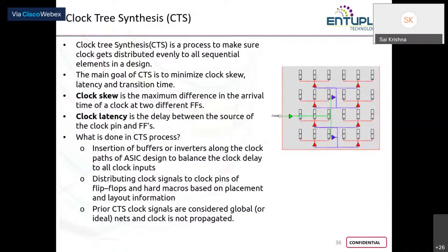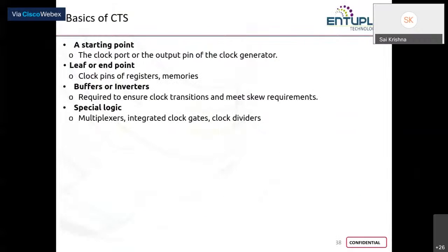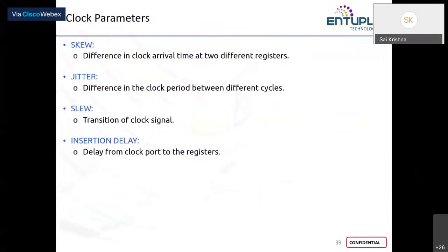So the inverter formed by changing the width of PMOS is your clock inverter, and the buffer formed using two clock inverters is your clock buffer. So for building your clock tree, we are going to use only clock buffers and clock inverters strictly. Okay, and your clock tree is not directly built. There is something called specification, clock tree specification, that is to be mentioned.